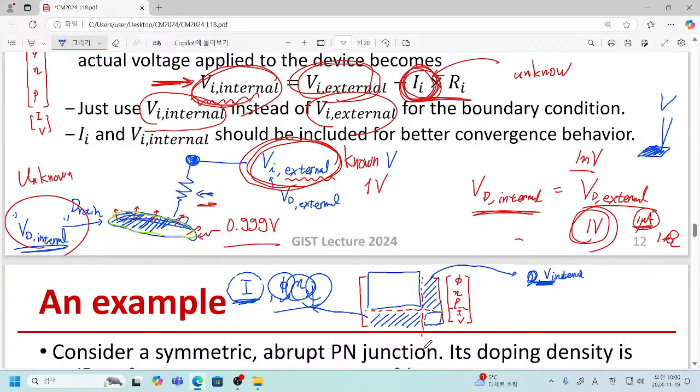It was not included in your Newton-Raphson method. But now you have to explicitly write down the expression for your drain or terminal current and calculate the Jacobian matrix for that contribution. So that is a little more complication obtained with this kind of constellation.